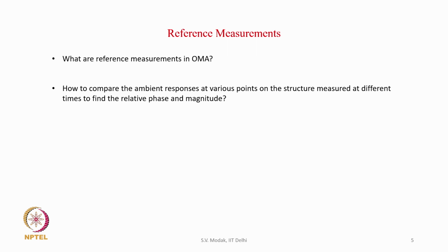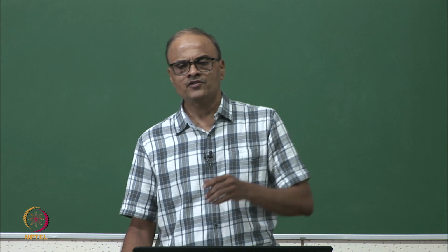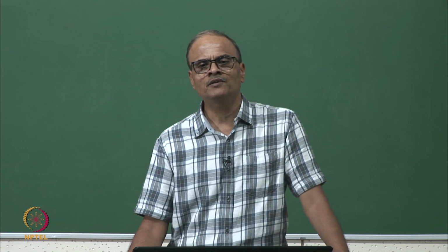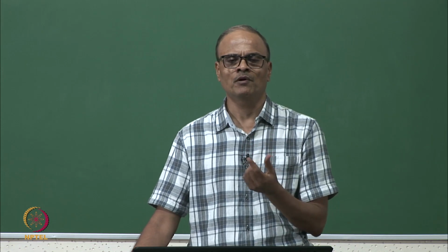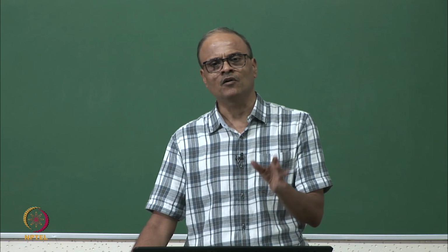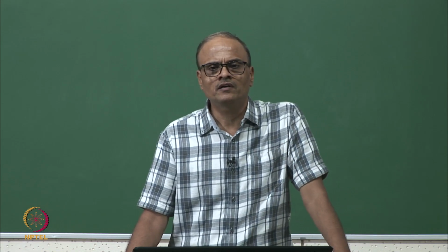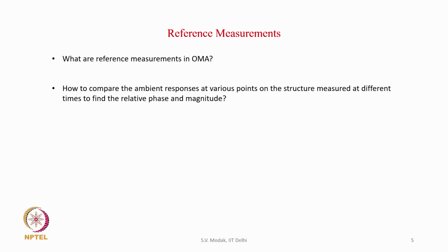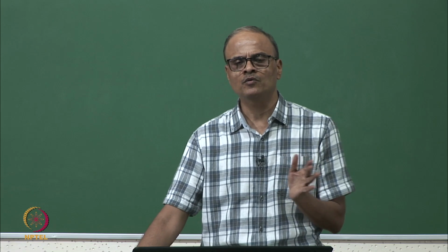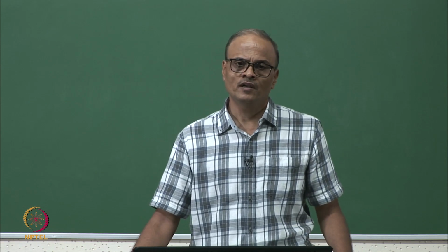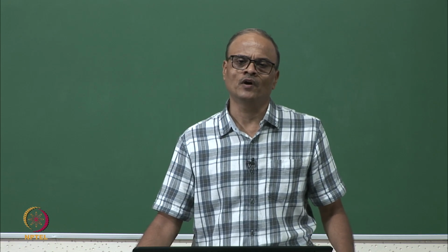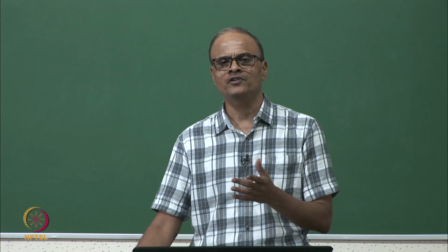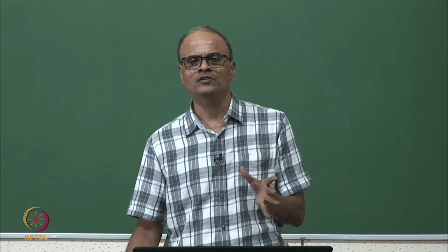In operational analysis we measure only the output responses, and generally for a large structure the responses may have to be measured at a large number of points. So, generally the measurements are taken in batches. We take measurements at a certain number of points and then repeat the process to complete measurements at all the points. Therefore, measurements taken at different instants of time correspond to different states of motion of the structure. Also, the excitation which would correspond to these measurements would in general be different, and therefore, these measurements cannot be directly compared to find a relative phase between vibration at different points, right. So, the relative phase and magnitude of vibration at different points cannot be obtained by direct comparison of these responses.